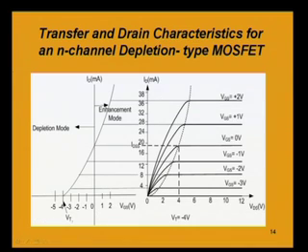Threshold voltage is minus 4 volt for this example, this is the point. Now, to the left, the MOSFET is in the depletion mode of operation. So, the current when it meets that minus 3 volt, this point,